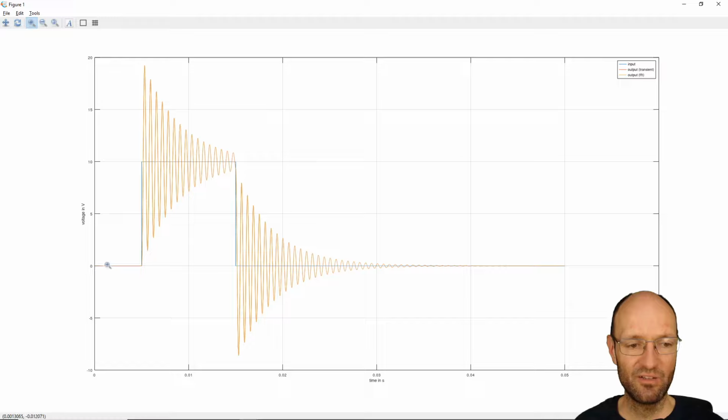So this oscillation that we've just seen happened here. The reason for this is that it's an artifact of the FFT. We are starting this oscillation, it's ringing, it's damped, and we switch off, it's ringing, it's damped, and still we have some very small oscillation here at the end. Now the FFT assumes that this time function would replicate.